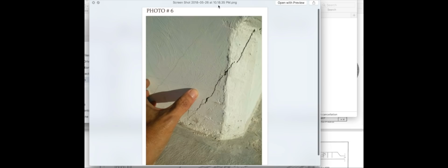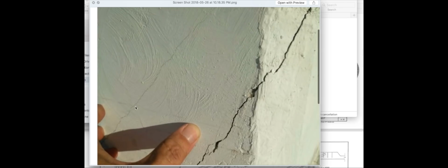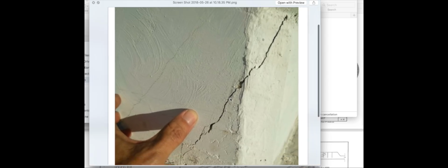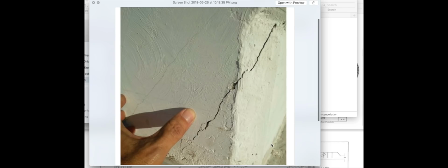So now we have this rod here that's supposed to have been tensioned. More cracks. He doesn't address that this longitudinal post-tension rods that are inside here are causing cracks. He's addressing this one. With that said, if this bridge deflects from the center, now if you guys can imagine a bow, deflection in the center, you would create a force on that rod that, if this is a pencil, the forces would be pulling downward. So you're going to get a crack here, going both directions actually, right? You got counter forces.